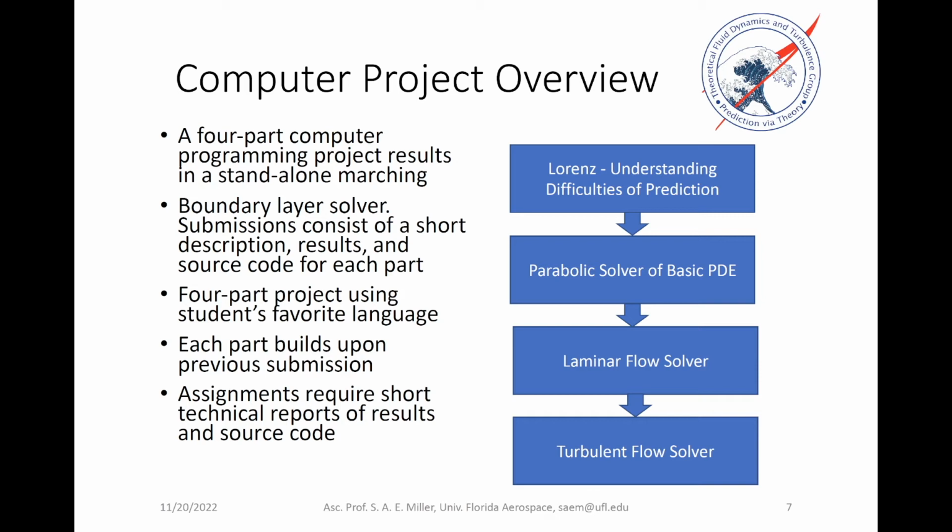Then we created a basic parabolic marching solver solving just a basic PDE, which is representative of a more complicated PDE relative to boundary layer equations. Then we extended that solver to the laminar flow, and finally we extended it to the turbulent flow.